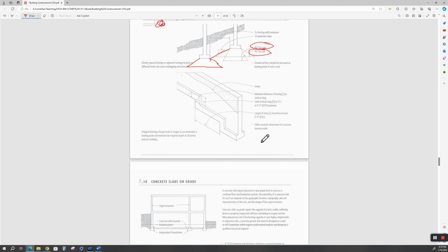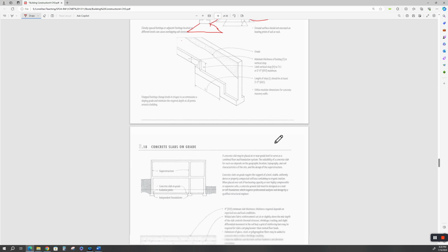Again, your structural engineer and you and your architect, or your soils engineer, should be able to guide you on this. So what this means is this footing is stepping up. So this footing does not go all the way back, super deep back in here where you have to do a deep excavation. You're basically benching or stair-stepping that footing. Those are a real pain.